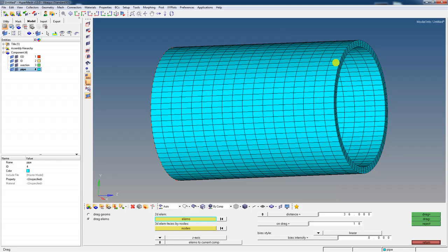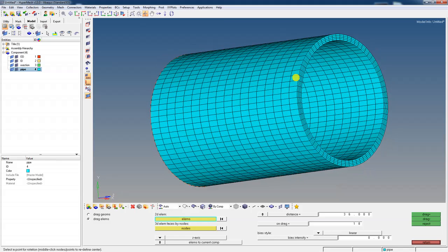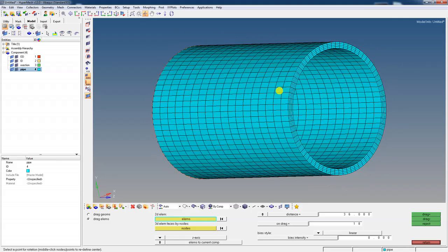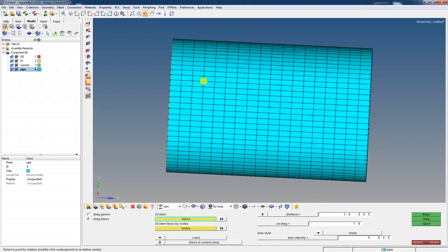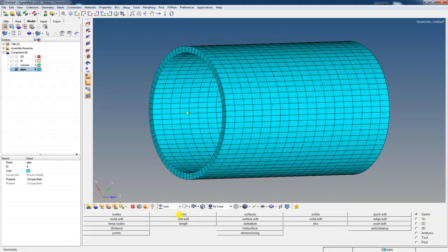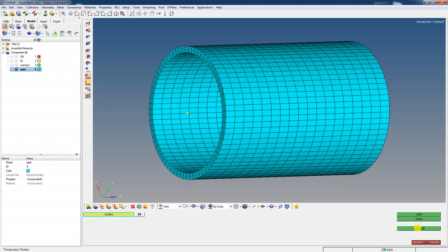The elements are a little bit skinny, but the edges, the angles are not very distorted. They're not distorted whatsoever, so that looks pretty good. Now when I save this mesh, I'm going to do what we did before. We're going to turn off everything that we don't need. I'm going to get rid of that temp node, otherwise it'll put that temp node in there.